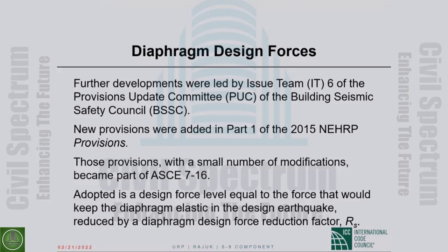Should I continue, Dr. Ghosh? Yeah, please. Okay, so this is a big question. In a dual frame structure, most of the stories are extremely torsional irregular, and the seismic force resisting system consists of more than two bays of moment resisting perimeter framing on each side of the structure, and in each orthogonal direction at each story, resisting more than 35% of the base shear. Can we still take the redundancy factor as 1.3 or 1?